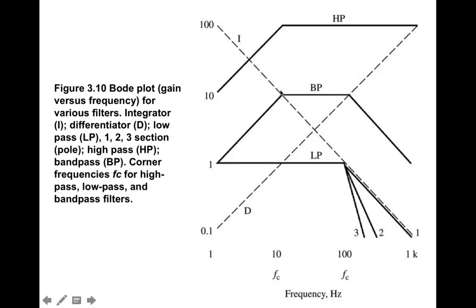So you basically have a range of frequencies that are passed where the output is equal to the input. And then on either side of that, you have a lower cutoff frequency and a higher cutoff frequency. This bandpass filter can also be built as higher order, so you can make these slopes steeper. And that's, in fact, often done.